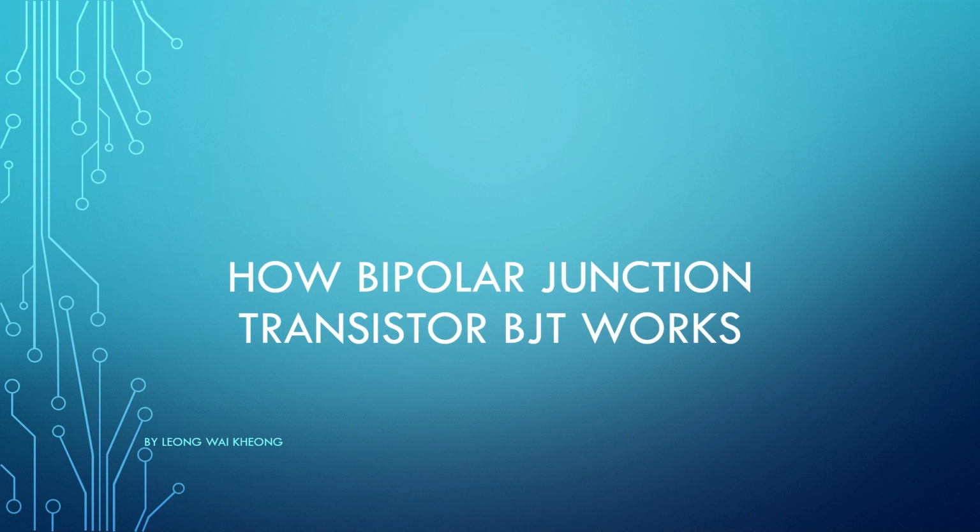In this video, we're going to look at how a bipolar junction transistor (BJT) works. Starting from an intrinsic semiconductor, we can divide it into three regions. The middle region can be doped with P-type semiconductor and the two sides are doped with N-type semiconductor. And this is an NPN transistor.